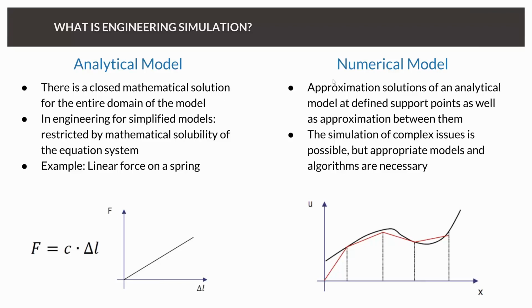These numerical models are based on the analytical models, but instead of calculating an analytical solution, they approximate the solution using defined support points and approximations between them. And this allows us to solve or calculate even complex issues. But for this, we need appropriate models and algorithms. And this is CFD. CFD is the idea that we take the Navier-Stokes equation, which is the equation describing the motion of a fluid substance. And since we cannot solve this equation analytically, we are using numerical methods to solve it.